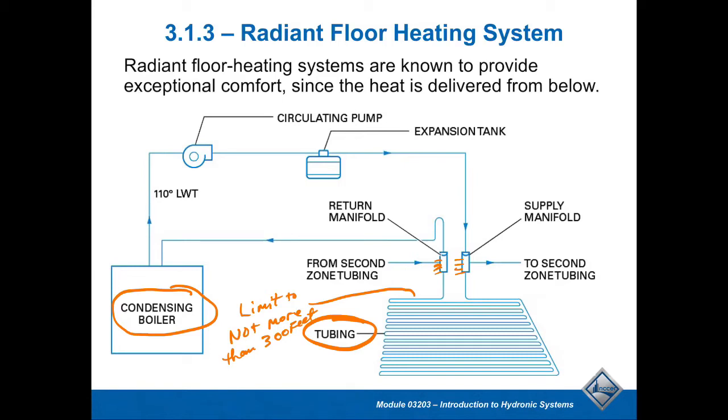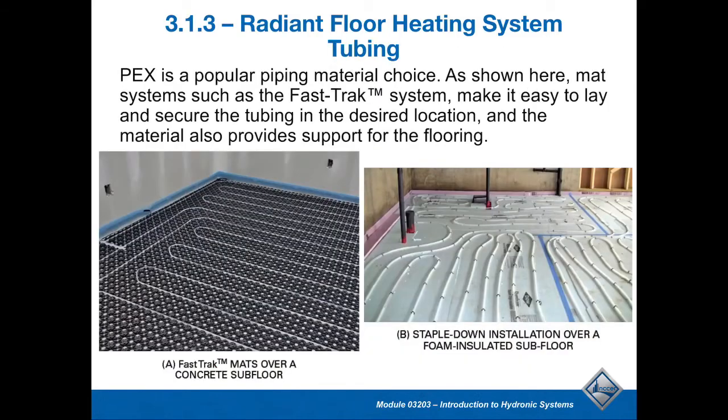So it just depends. These types of systems really need to be laid out and planned out to make sure that we have the right lengths of loops and what water temps. So they can be unbelievably comfortable for the system, but they have to be properly set up and designed. So that is what is needed. Here's a good example of this one here, showing the PEX. Now this one over on this side here, it's an awesome little fast track system where these little grids are popped into there and you'll snap all that in there.